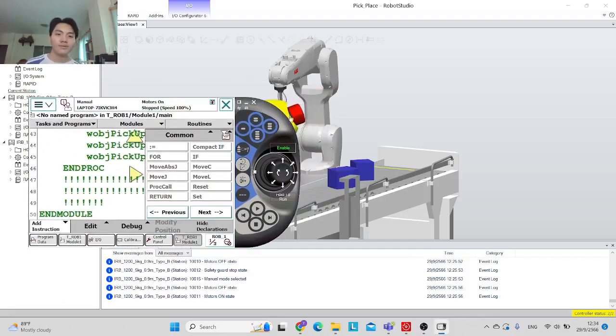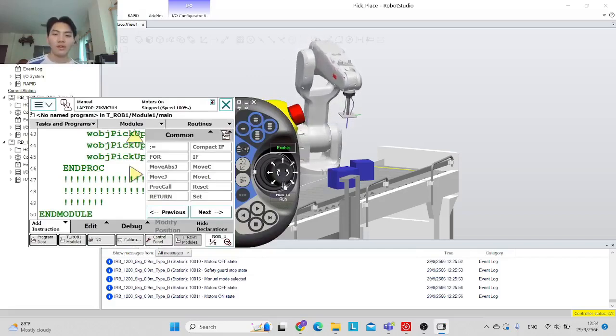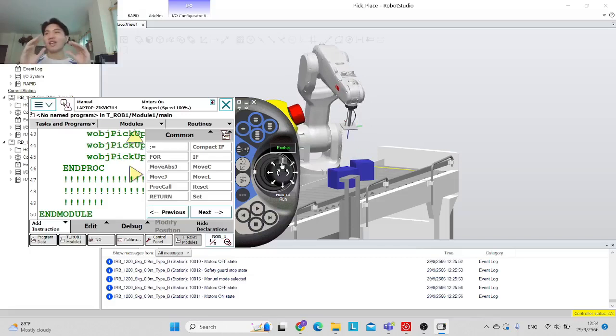And you give it a part, or you can jog by manually, something like this, and then you move it on this, and you can set the position, and it automatically gives you a code like a move J 500, move L 100, something like that. All right,